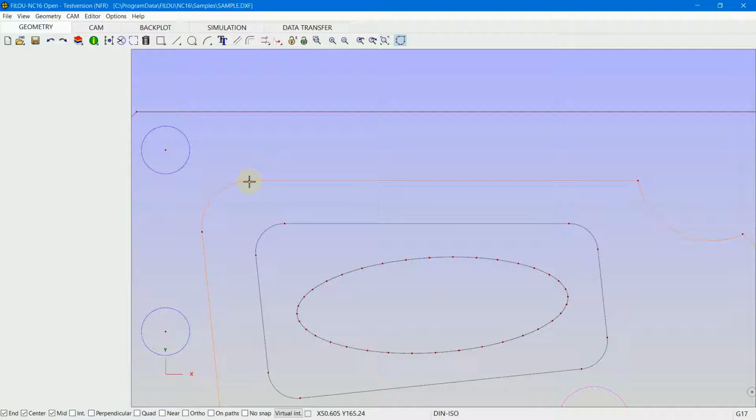This seems to be pretty clean. When we look at this, it does not look so clean. It has a lot of points, which can be okay, but I think it can be easier or more simple. I know it was an ellipse that was converted to arcs in order to use it in our program and to make NC code of it. This means if it is an ellipse, then this point and this point may be too much, perhaps not important.